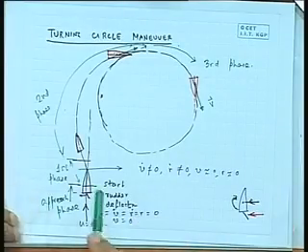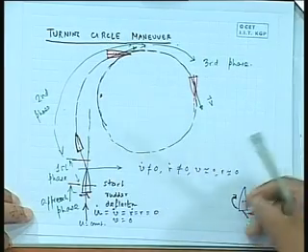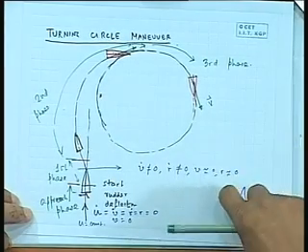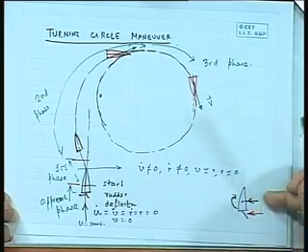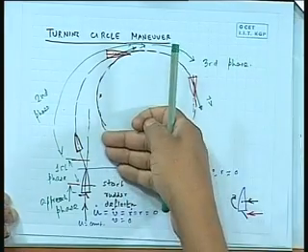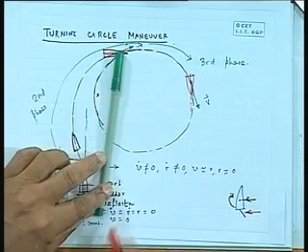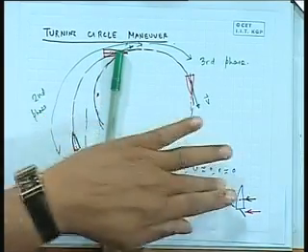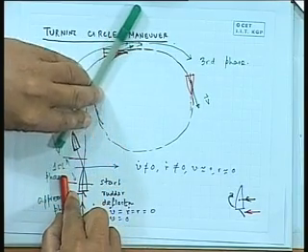Yeah, exactly. Initially it always yaws because there is a push here. So what happened, that part I will come to, why this swings here: because of this force initially, before it has a chance to change its heading angle, this force is dominant, so the full ship has come slightly on this side. You notice that I give the rudder angle here, immediately there is a force coming this side, so it first shifts slightly this side, then only it gets a turning angle.